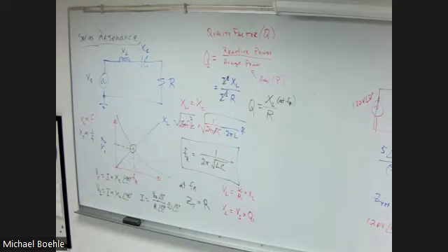So if I have a Q of 10 and I apply 5 volts peak to peak to my circuit, that means I'm going to have 50 volts across my capacitor. Yes. And your inductor. Now, before you get all excited and say, ooh, a multiplying circuit, nah, that's not exactly. Because as soon as you try and load it, as soon as you put anything in parallel with your capacitor, you completely change the dynamics of the circuit, and it doesn't work. Okay. But you will see a multiplying effect.